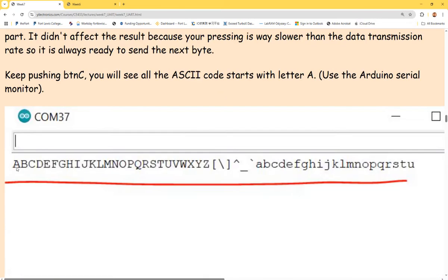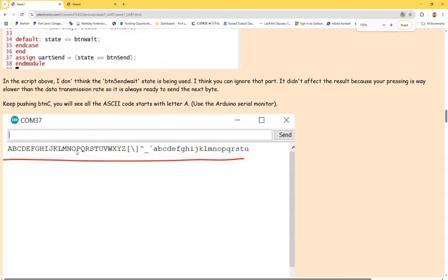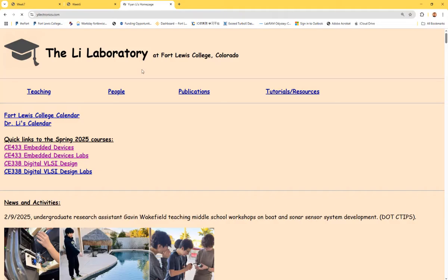And then what the top does is it receives the signal from the button. It debounces the button. Keep in mind, it debounces the button, right? Receive the press. If you press it, it's detecting a rising edge or falling edge. I should add it to the exercise. Where can I find it? If you press the button, is that the rising edge or falling edge?